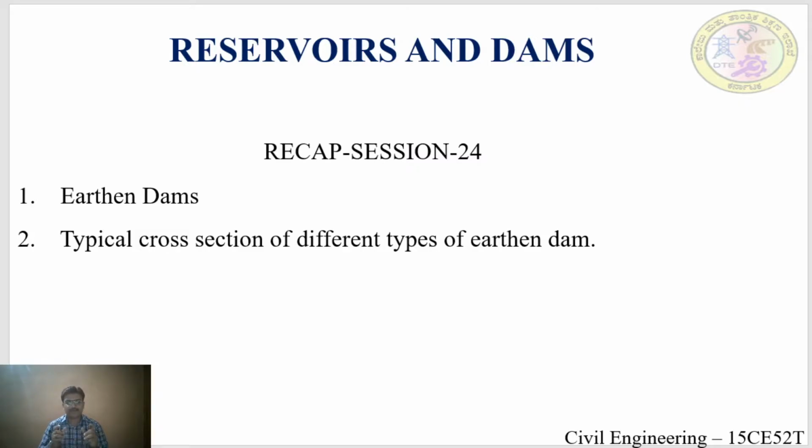The pervious shell is present both at the upstream face and the downstream face. There is an impervious core present in the center portion of the dam, and the transition filter is present. The horizontal drainage blanket is provided at the toe portion of the dam.